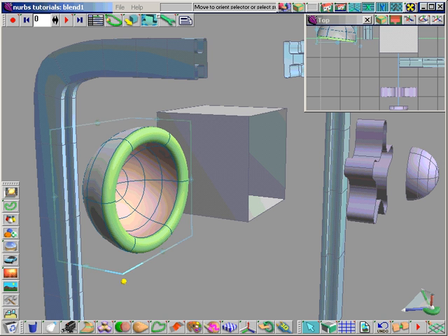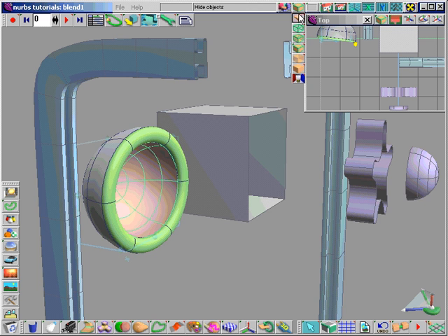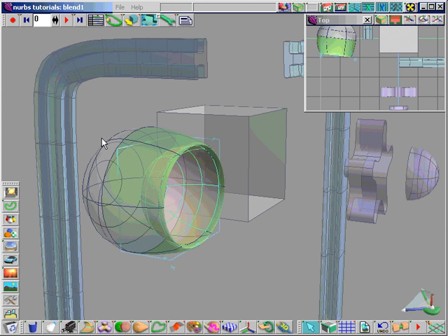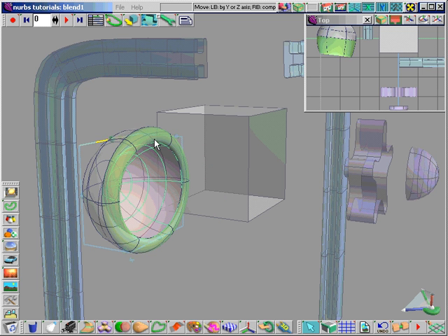The blend itself can be undone or selected separately in hierarchy and deleted. You'll have to use the Convert to Plane Patch tool to edit the surface separately from the source edges. The object controller can be difficult to see in hierarchy situations. Switching to transparent outline mode lets you see the entire box, and then it's easy to manipulate the source objects. The blend surface is dynamic.